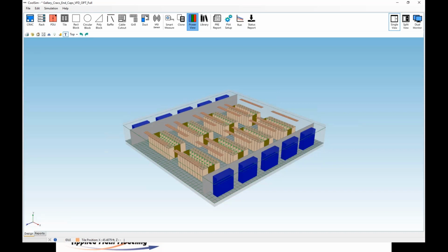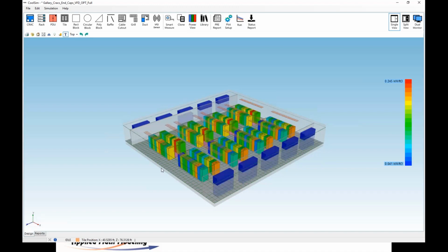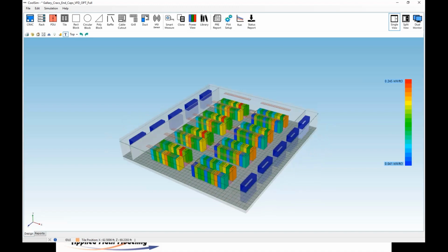So what you have to do is use good engineering judgment to try to steer things in a direction that is going to be good for the customer and good for the prognosis of the data center over time. So in this case, what I did, instead of loading those uniformly, is I loaded them in a particular way that varied the load across those racks. And here's a plot of how I loaded them. This is a load plot here. It's called Power View that we have.